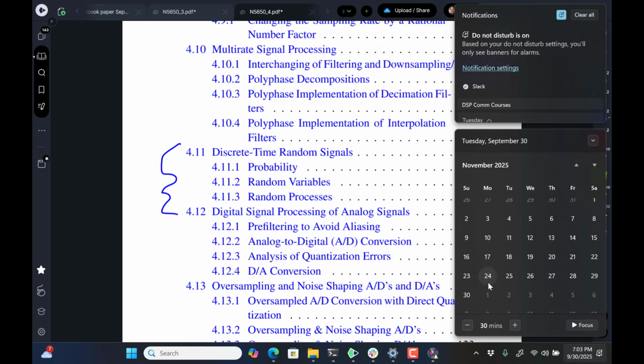Now, it's foiled me in the past. The simulation side, I would think the person would see that their theoretical calculation was wrong, but they make the same mistake sometimes, and they get an agreeing answer. It's like, these two agree, I must have done it right. No, you made a mistake in both of them in a different way. But the idea is to cross-check things. Just like in this assignment, the residue Z is helpful to check things out.